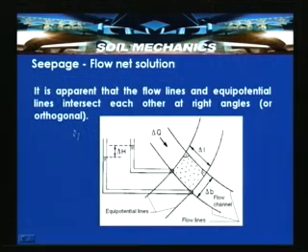So, from the theoretical deliberation, you see that the angles where both flow lines and equipotential lines meet are orthogonal. This orthogonality of flow lines and equipotential lines has to be kept in mind while constructing flow nets. We will be using that concept, and we will be considering different types of structures with confined seepage conditions and unconfined seepage conditions. Confined seepage conditions are basically with sheet pile walls or a masonry structure embedded in a permeable soil medium, and in case of unconfined seepage conditions, flow through an earth dam can be considered as unconfined seepage.